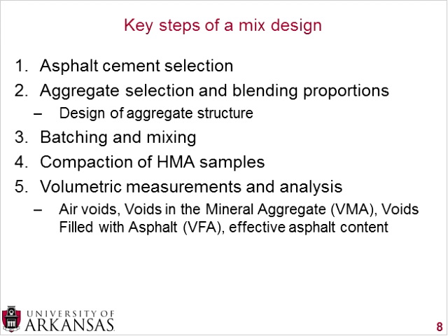The key steps of a mix design, we'll get into more details on each type of mix design, but they all follow approximately the same steps. You want to have your materials selected, both your asphalt cement and your aggregate. The aggregate is important because you can take different sources of aggregates. So if you have 4, 5, 6 stockpiles, they can be crushed rock, they can be river gravel.